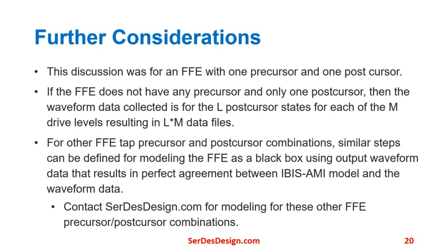For other FFE tap precursor and postcursor combinations, similar steps can be defined for modeling the FFE as a black box, assuming output waveform data that results in a perfect agreement between the IBIS-AMI model and the waveform data. Contact SerDesDesign.com for modeling for these other FFE precursor-postcursor combinations.